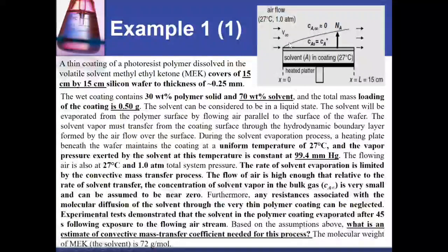Yes, Shabab. Doctor, isn't the statement that it's dominated by convective mass transfer the same as saying there is no resistance in molecular diffusion? Yes, they are similar. If we write assumptions, we only write one of them. Any resistance associated with the molecular diffusion of the solvent through the very thin coating can be neglected. This is similar to this one, that the rate of solvent evaporation is limited by convection. So they are almost serving the same purpose.